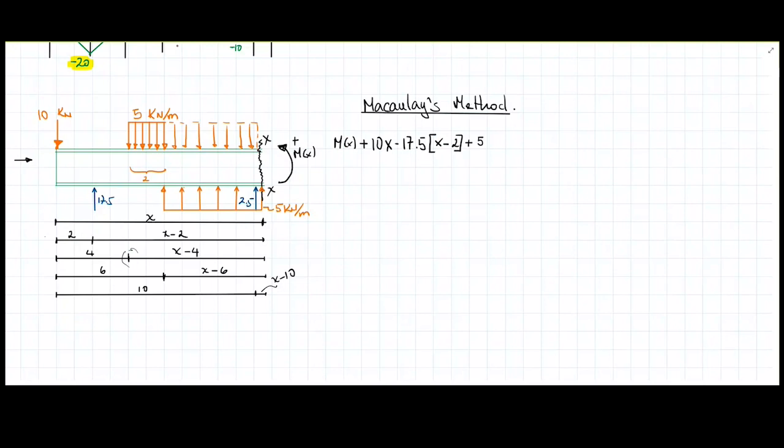So that's going to give me the magnitude of the force, x minus 4, times kind of the middle of this till that. X minus 4 divided by 2 would locate me in this point here, and that's going to be the arm of the moment. And then I can write this as square and then divide this by 2.